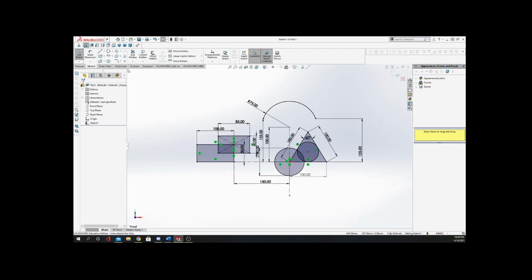So if we scroll down a little bit, I can show you some of the other arc tools. So we have this tangent tool. Do you remember how when we were drawing the line originally in the beginning, and I went back to the point and it started doing the curved line? That's what that is. I just picked a point here, and from that point, I'm able to draw an arc. And then you can keep on drawing arcs as you go down, or you just push escape and it brings you back.